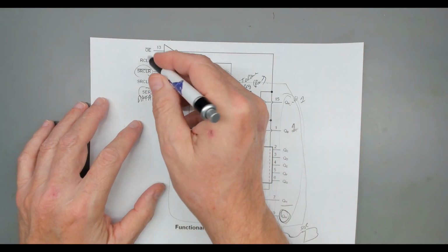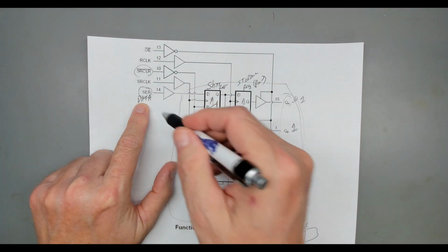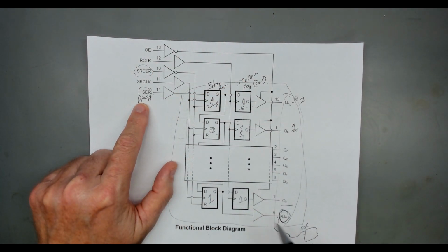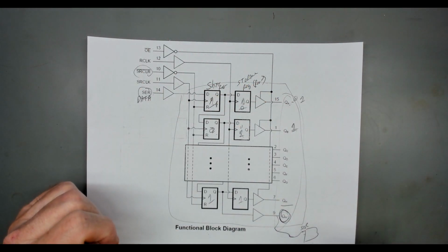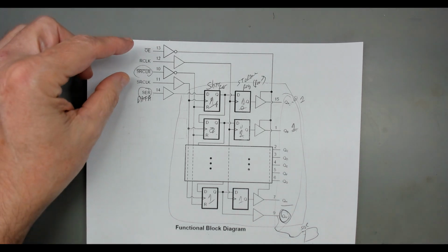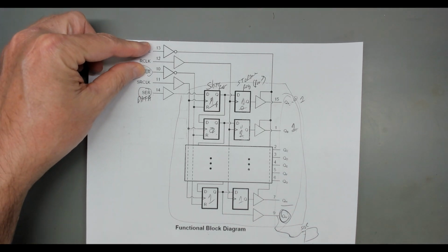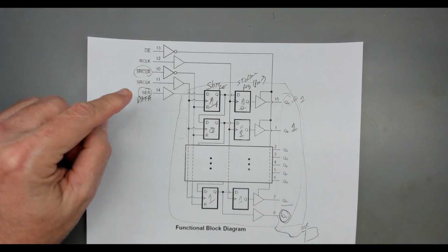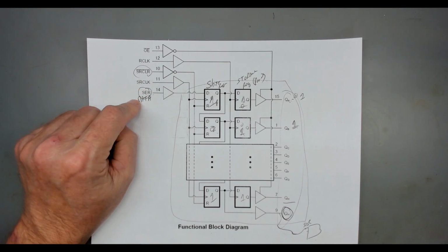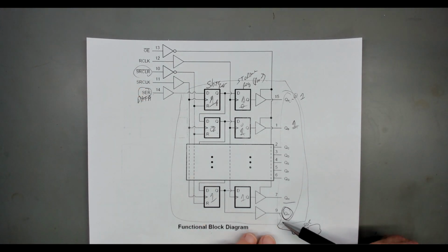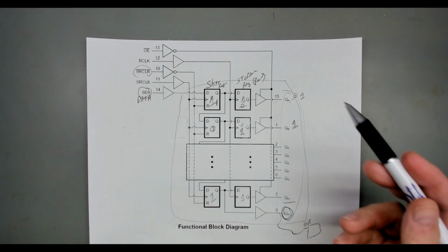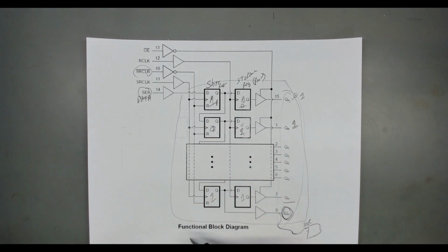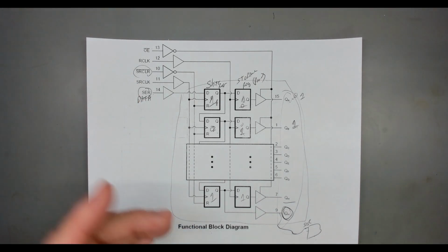And all the other lines, this line you won't bring over to this chip. It gets it here. But the other lines, you just come off of these and run down parallel to these other chips. So however many chips you put on, you hook these lines the same way to each one of them, and then the first chip's serial line gets the data from the microcontroller, and then each chip's QH out goes to the serial of the next chip. So the data just flows right down through however many chips you put in line there. So you can put in serial a lot.